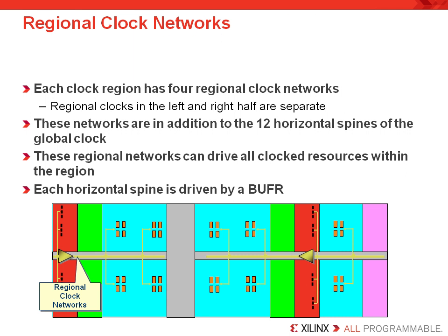Regional clock networks allow additional clocks to be distributed to the clocked elements within a clock region or area. And some regional clocks can also travel into neighboring clock regions. Regional clocks allow more clocks to be used in a single design as long as those clocks are not needed globally, but only among one or two neighboring clock regions. Regional clock networks reach the clock inputs of all the synchronous elements within that clock region.